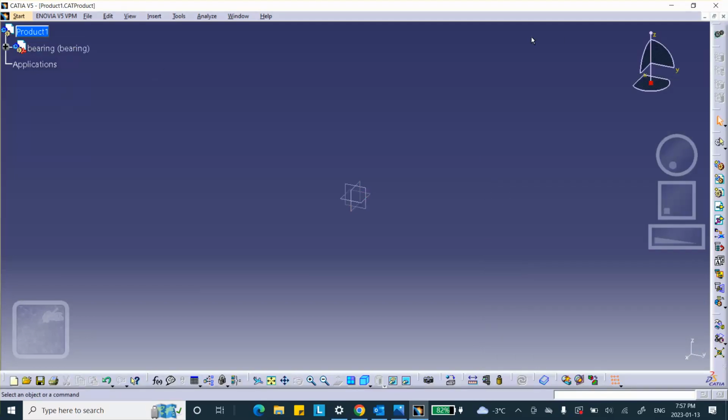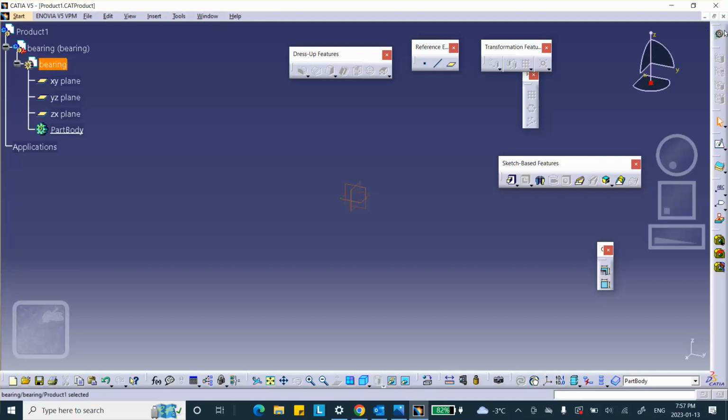All right, now to create the part, I have to be in part design. This is not part design; two gears means you're in assembly design. So I expand this thing and I double click on this line. And now notice that I'm in part design. By the way, if this is dimmed, that means you have selected the tree for some reason. So let me click on any of these white branches. Actually, the thing is no longer dim. Or if you click on this axis down here, in the right corner, the dimness goes away. So on this vertical plane, I will sketch